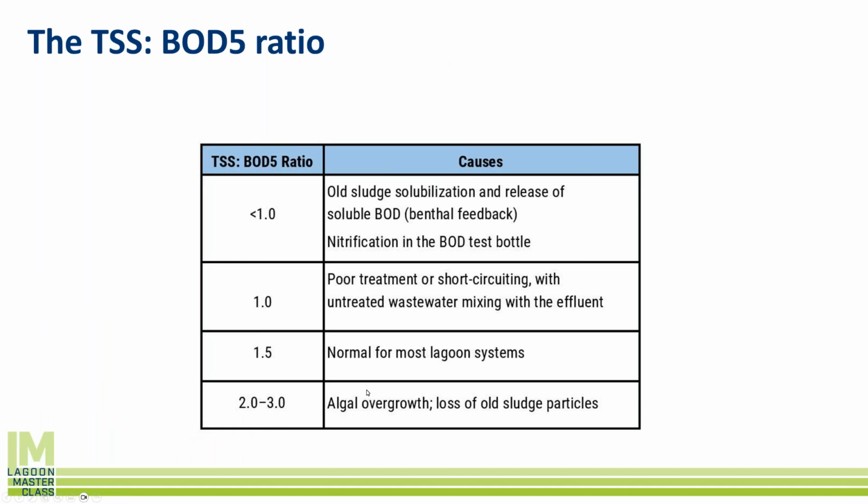So again, I like this chart because it's a really great rule of thumb that gets me pointed in the right direction to say, hey, do I need to go out and maybe take a soluble BOD reading to make sure it's actually soluble versus total BOD? Do I need it? So it gives me some ways to diagnose this.